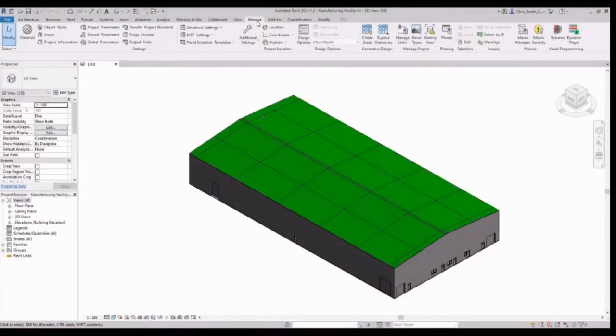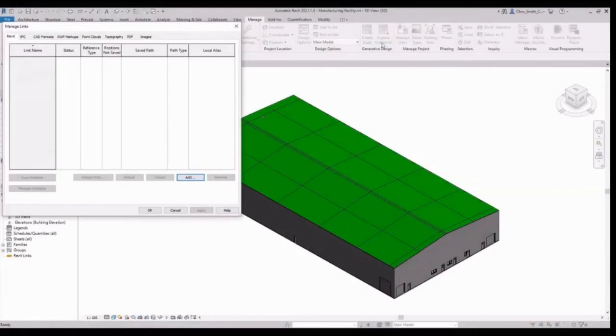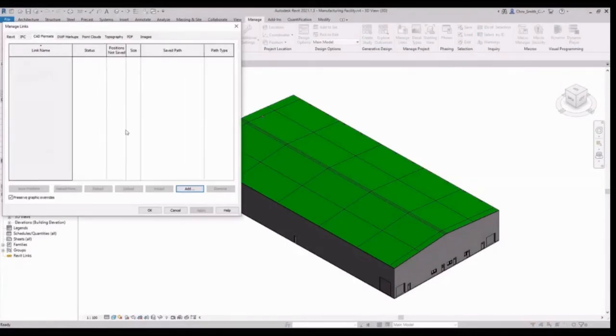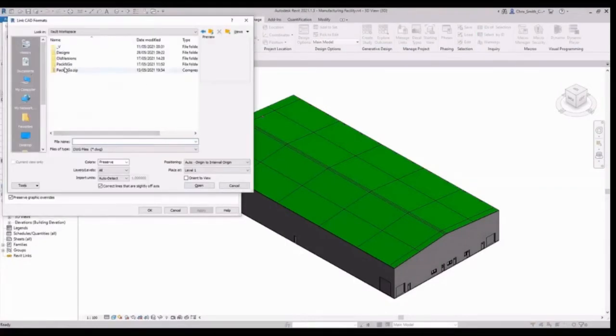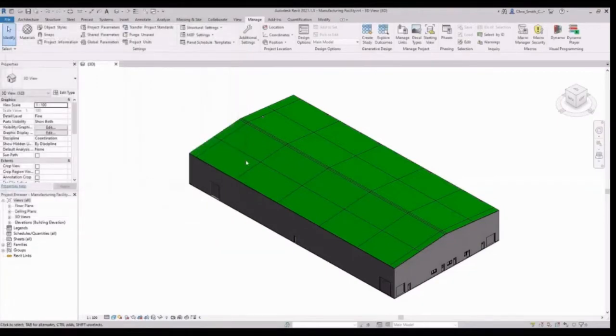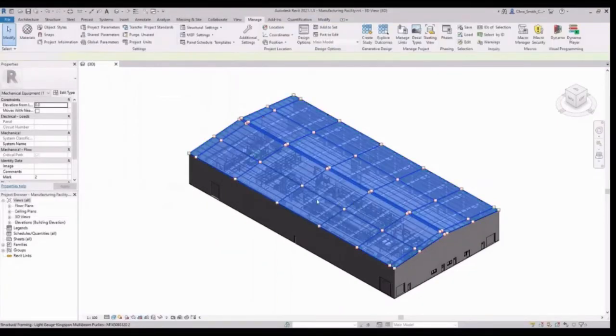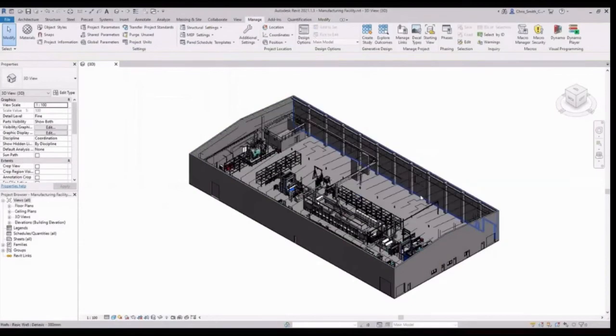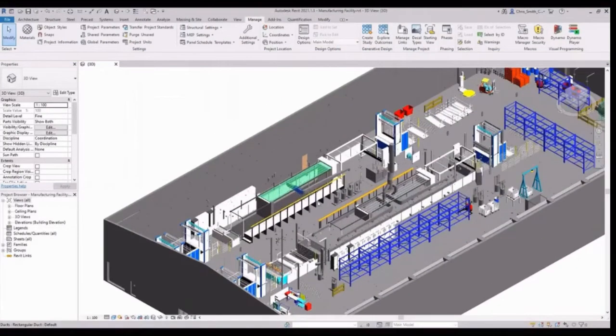Back in Revit, the DWG file can then be attached to the Revit model, and because our factory was created using the original Revit World Coordinate System, we can again import the factory layout to the origin point. Once the DWG has imported, we can hide some of the Revit elements to see inside the model, where we can see our factory elements within the Revit model.